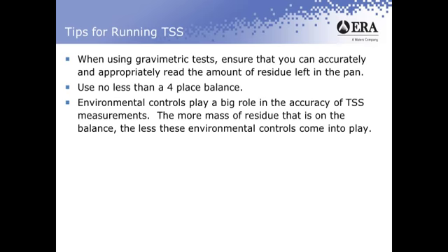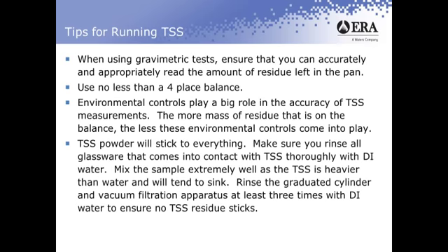Another issue with TSS, as you know when you're doing the tests, is that TSS tends to stick to everything. So what's real important to minimize any of the sticking of the TSS powder is to make sure that you rinse all your glassware thoroughly. Anything that comes into contact with TSS, you want to rinse with DI water. When you're doing your test, you're going to mix up your sample real well. I would recommend inverting any samples a minimum of 3 to 5 times to make sure that you get a good suspension.